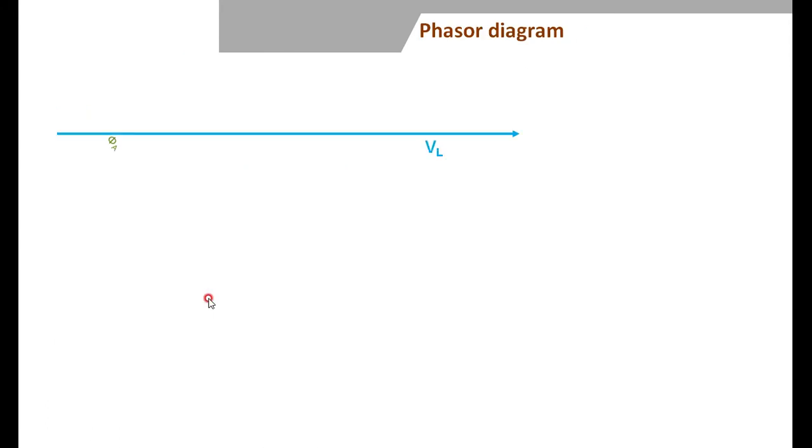For that, if you are drawing a vector diagram, the voltage across the terminal is taken as the reference first. Then the current IA is supplying the load at a certain power factor. Then to this V, I have to add IARA, which is parallel to I. Then I have to add IAXA to the IARA, which is perpendicular to I.